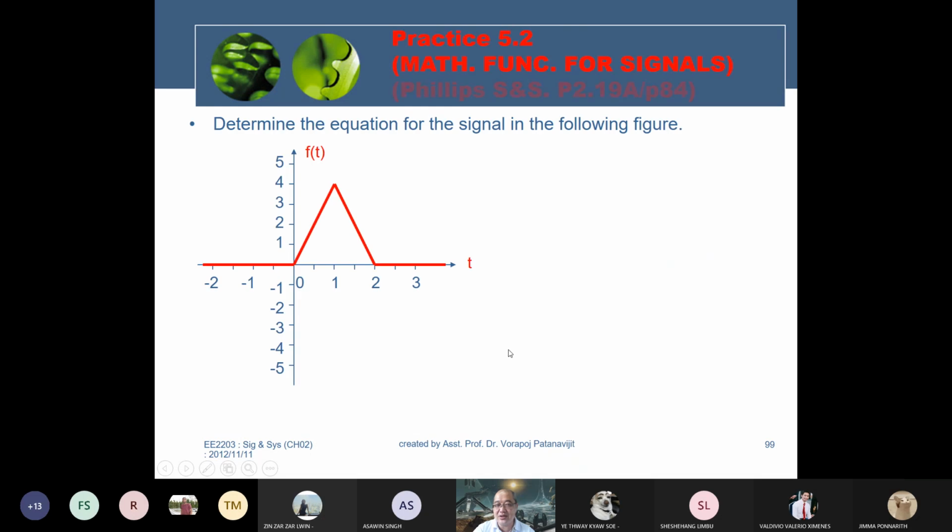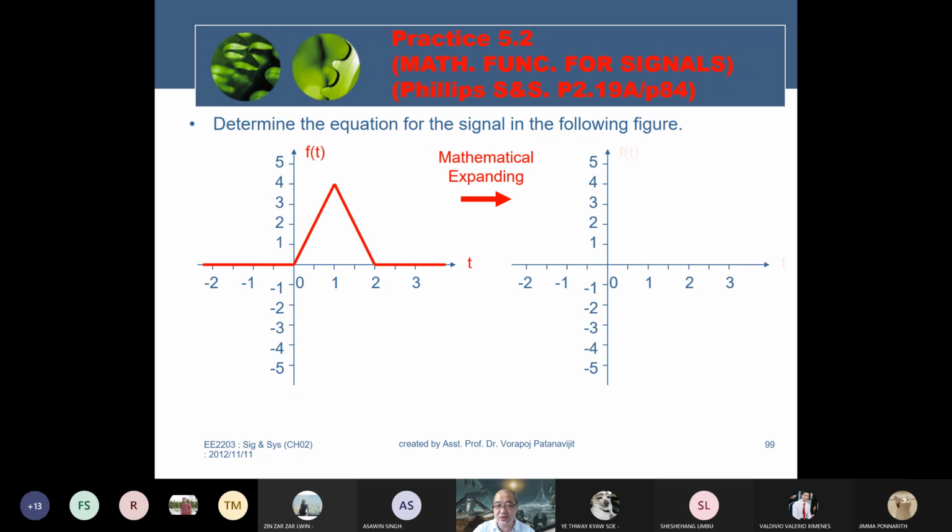Next one. The next one is a little more complicated than the previous. This graph has a ramping function, and therefore it requires t u(t). In this case, how many mathematical terms do you require? Changing the slope at the first point requires one term. Changing the slope or the value requires the second term. And the last one is changing the value again. Therefore, in this case, you have up to three terms.